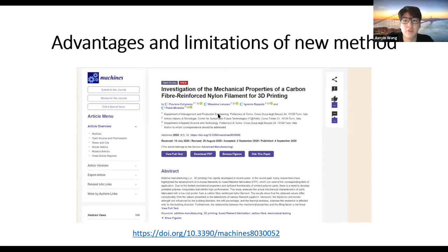The tensile stress and the stiffness of the composite sample were 60.69 MPa and 8.91 GPa, respectively, whereas these values for a pure ABS sample were 29.31 MPa and 2.05 GPa, respectively.